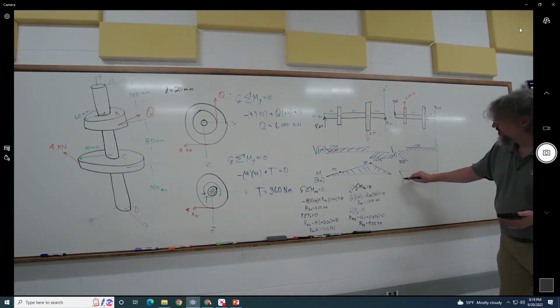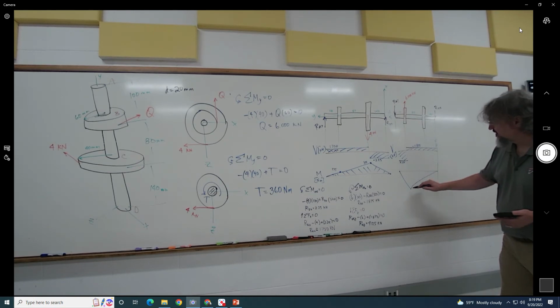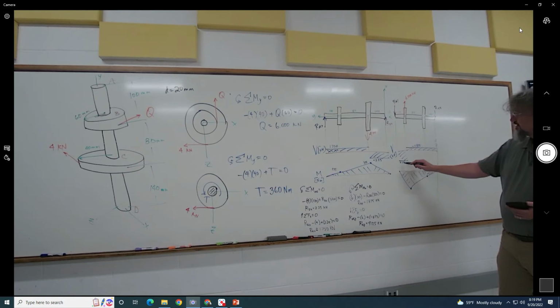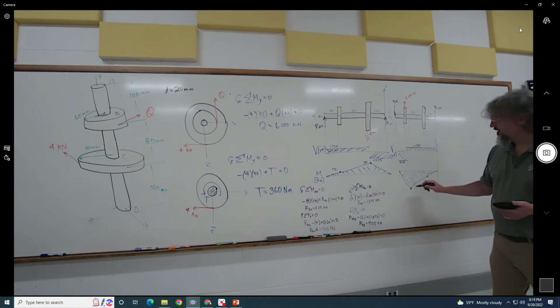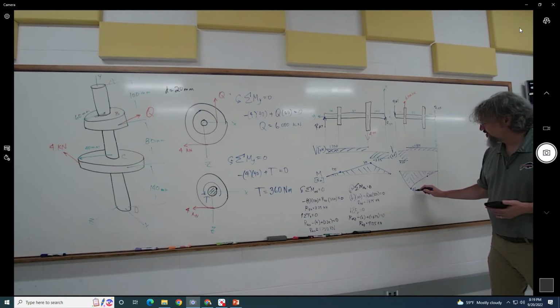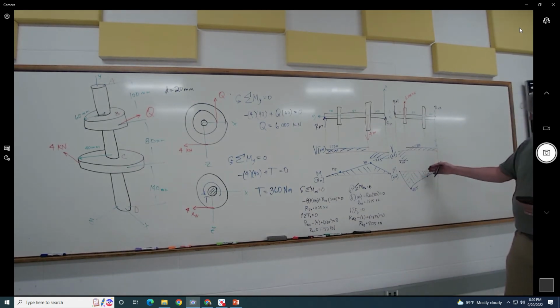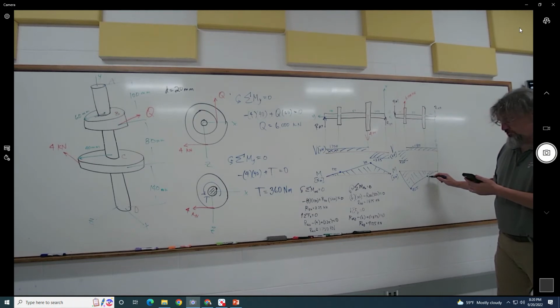This one down here is going to be fairly steep, where it's not going to be as steep right there, and I'm doing a terrible job of that. But we want to get both of them. We'll take the 4.125, multiply it by 100, I'm feeling bold, 412.5. These are Newton meters as well. And it's easier to go to the other side, so it's 140 times the 1.875. And that should be 262.5.